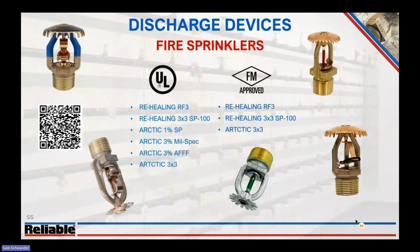So these foam concentrates, as Mark and Pat discussed, are going to be UL listed, FM approved, or both with specific sprinkler models. The sprinklers are going to have unique design characteristics based on things like orientation, whether it's upright or pendant, K factor, right? 5.6, 8.0, 11.2 K factor. So this list here is detailing all the Perimeter Solutions foam concentrates that are UL listed or FM approved with fire sprinklers as discharge devices. And again, that's what that QR code is going to take you to.